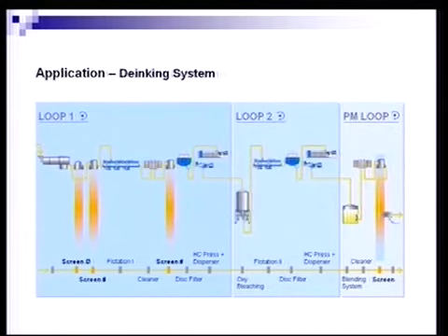Screening plants in a de-inking system, on the other hand, also follow pulpers, would be coarse using holes, fine using slots, then followed by, in this case, flotation and cleaning and other unit operations, and then at some point would usually see fine screens again, that is slotted screens prior to dispersion for final removal of sticky debris or other contaminants.